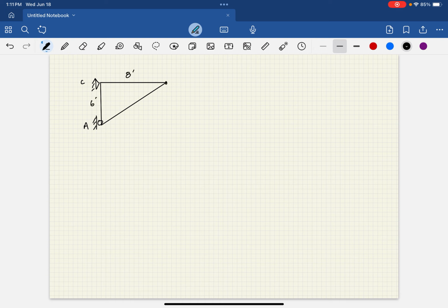So what's going to happen at this joint over at B? Well, here we're going to say P plus 150 pounds. So again, we're putting the variable load there, but we're keeping the 150 there. So it's like they're stacked on top of each other, okay? And there's joint B.